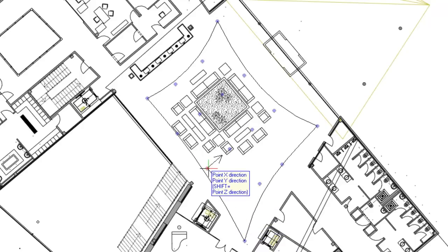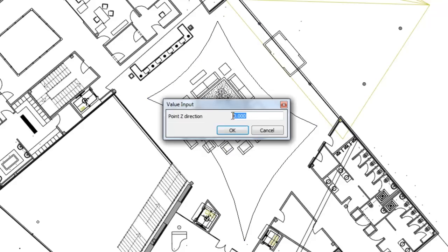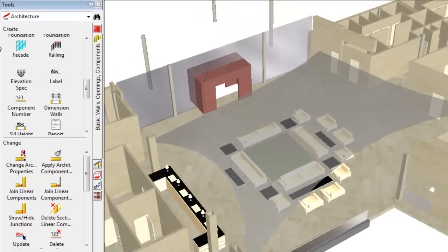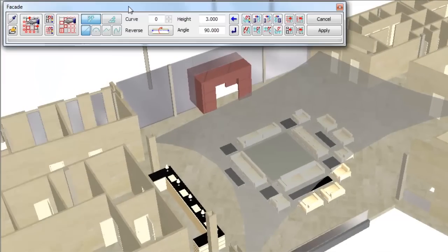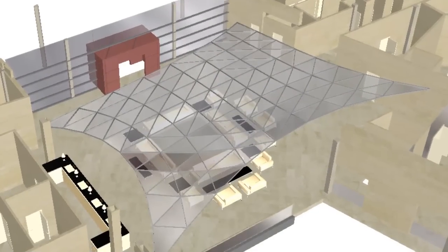Now it's time for the lobby in our project to be equipped with an individual design element in order to give it its unmistakable appearance. Starting with a simple surface, we produce a free and individual form with the handles of the SmartPart being moved around and values for the height being input. It takes just a few steps to turn the free form into an interior design element that can be created and evaluated and which has striking individuality and is easily recognizable. And this is how SmartParts help to turn ideas and draft concepts into a reality.